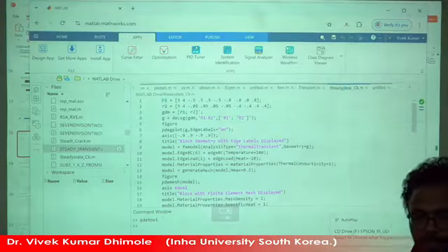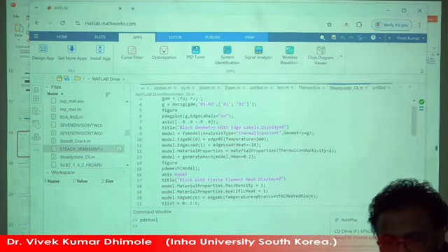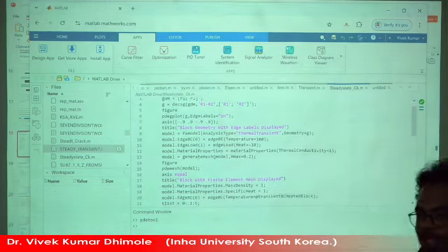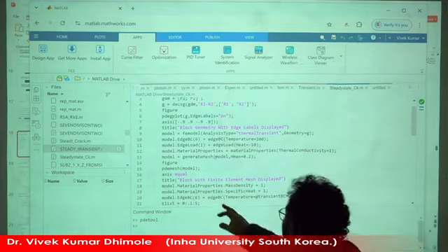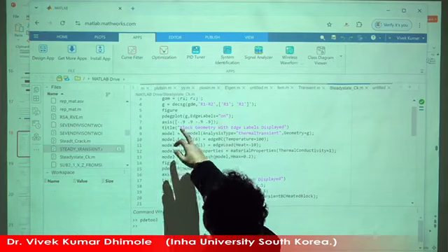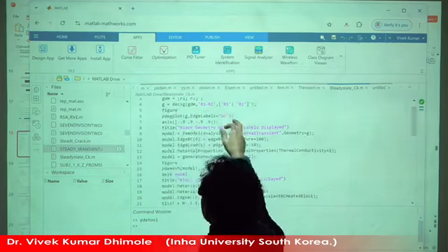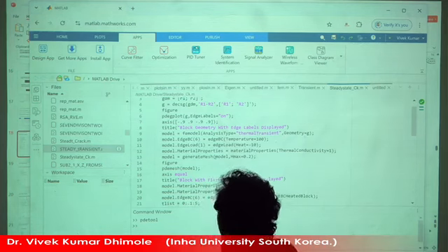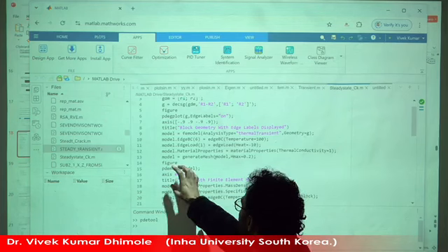See here, directly it's using, right? See, A is boundary conditions, generate mesh. See, this is a function. Generate mesh is a function. Writing the spelling as given becomes a function, right? Generate mesh, edge load, edge BC, title, PDE plot. This is the diagram you are making, right? And material properties, my model, means you are assigning. See, this is the complete model.